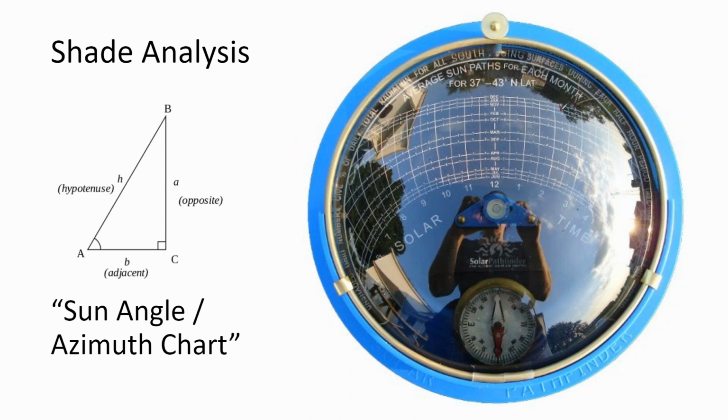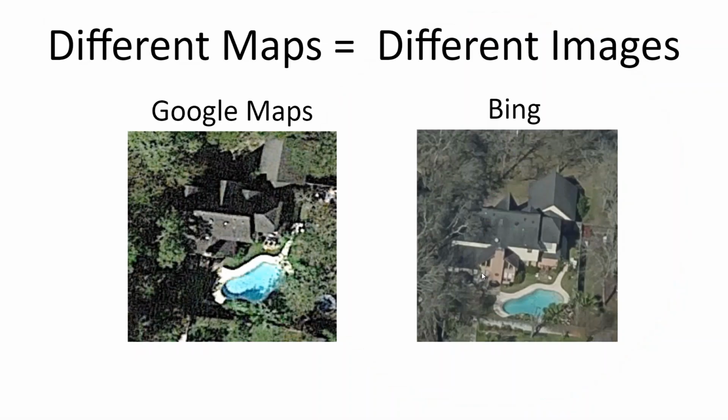There are even charts where you can use these numbers underneath, or you can find the process online, where you can take that section of the tree and convert it into a percentage. There are maps where each of these numbers represents a percentage loss of production. So you could say, okay, I'm losing an additional 1.5% because of that tree. That's a lot of work. Get up on the roof, walk every inch of it, make an accurate map, trusting this little compass.